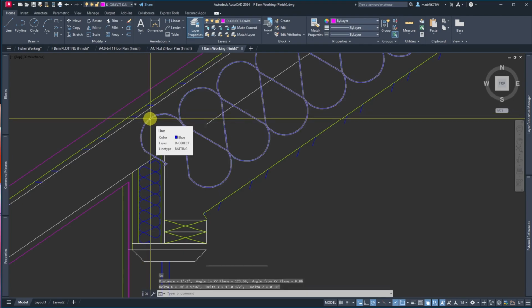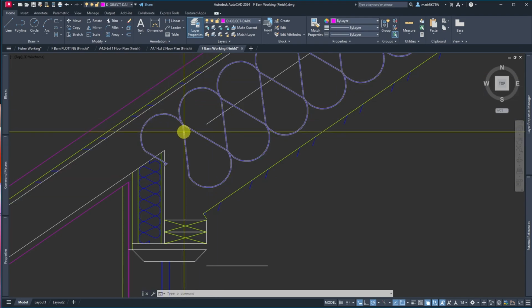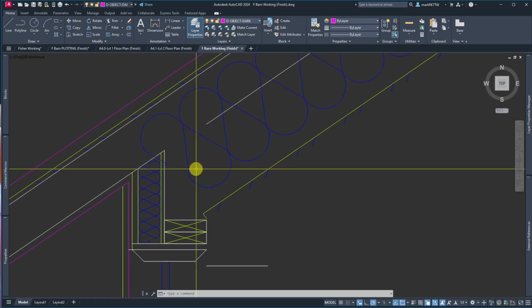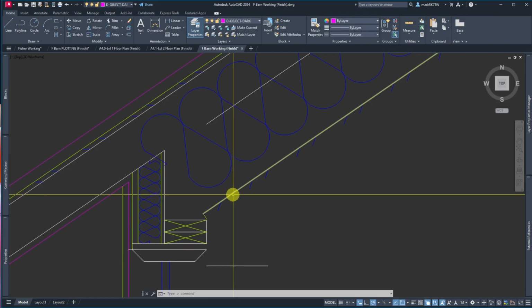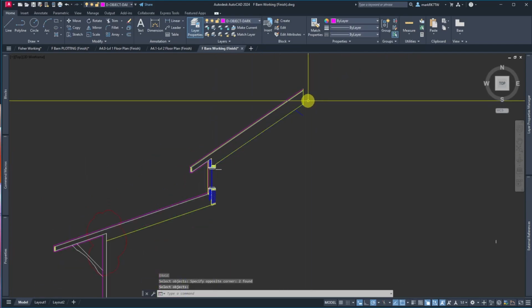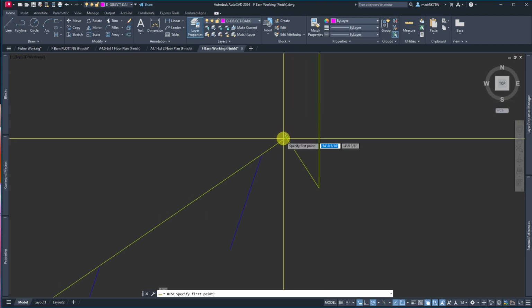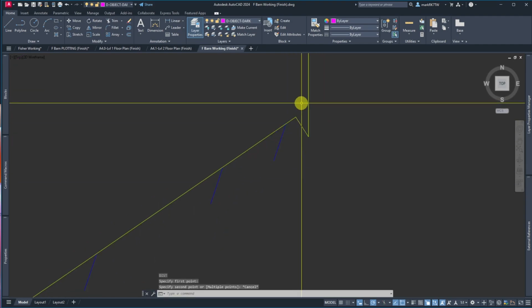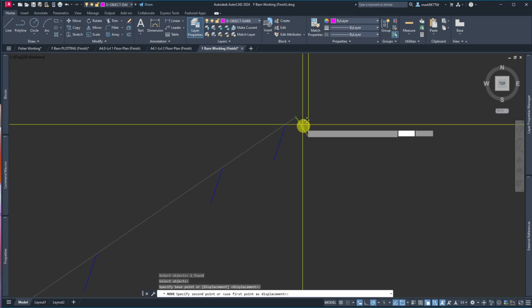It is 1 foot 3, which is 15 inches, which is our insulation depth. We need 15 inches of insulation to get the R60 if we're using mineral wool. So this line here is our interior line of the ceiling, but then we have tongue and groove, so this should be 3/4. Okay, so I'm just going to move this from here to here.